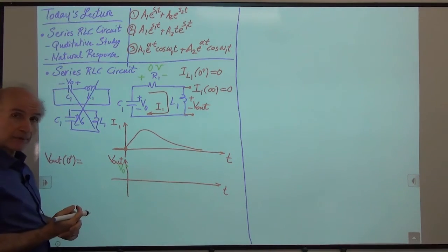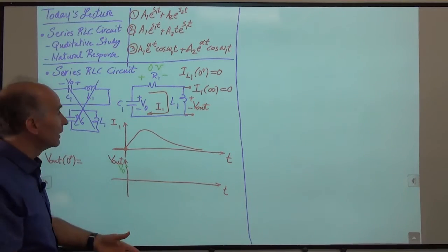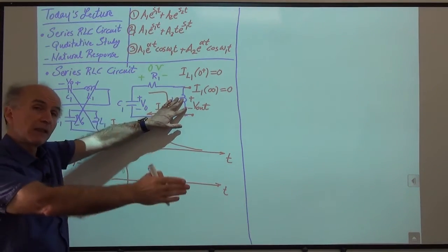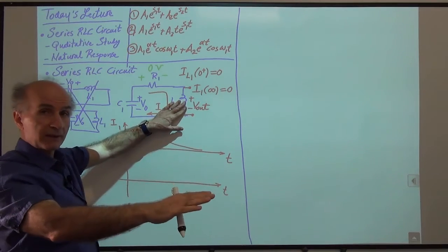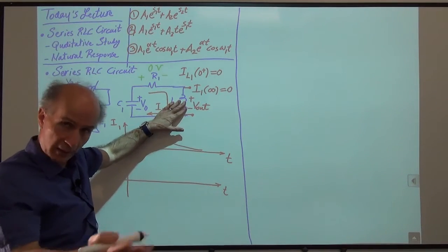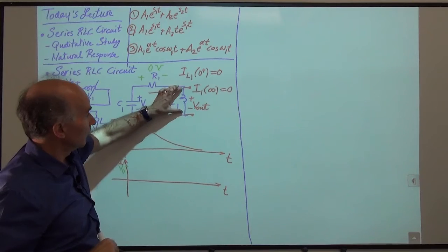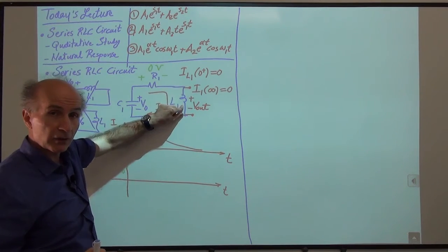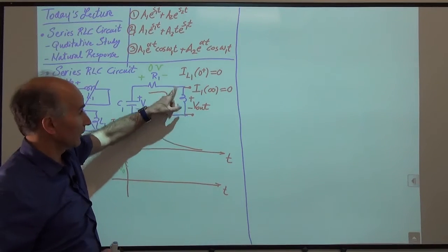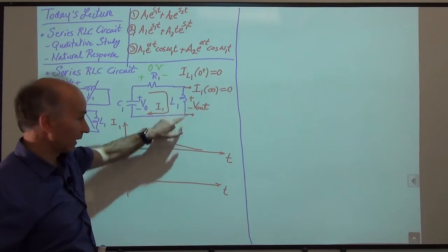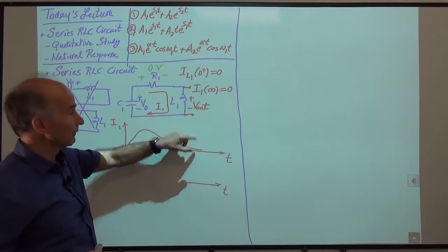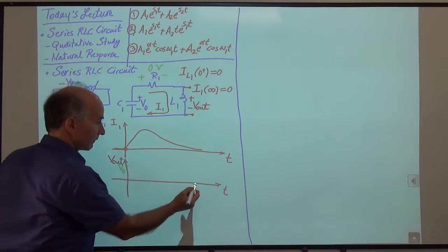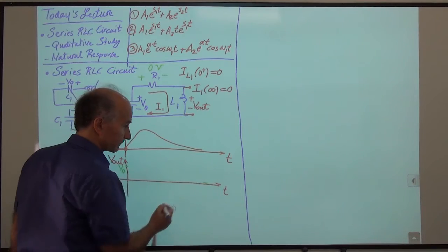All right, then what happens? Okay, so as time goes by, V out has to go to 0, right? Because we know at time infinity, all of the quantities have reached a constant value, and 0, of course. So if the current through the inductor has reached a constant value, then the voltage across the inductor is 0, right? So the voltage at infinity is 0, somewhere around here.